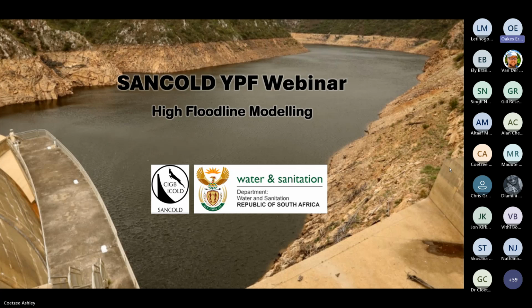The first question was getting the dimensions of the spillway into the model. It is quite important if you don't know what the discharge rating of that spillway is. So you do need to try and model it as much as possible, with your weir coefficients and your widths and that type of thing put into the model, just so you can increase your model accuracy. But if you have a rating table, it may actually become a bit easier for you. Brandon, I don't know if you want to maybe add to that, but that's my 2 cents.